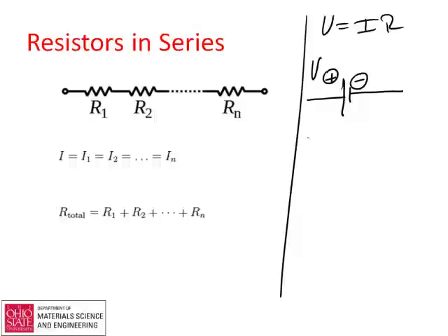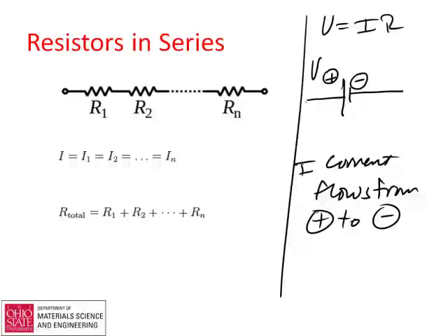When we've got current, we say that current flows from positive to negative. So what we would have is we make a circuit out of this and allow the current to flow like that. We've got to complete that with a circuit. We would say that the current would be flowing this way, like that, flowing from positive to negative. But that's just our definition of current, but really electrons flow the other direction. Electrons flow from negative to positive.